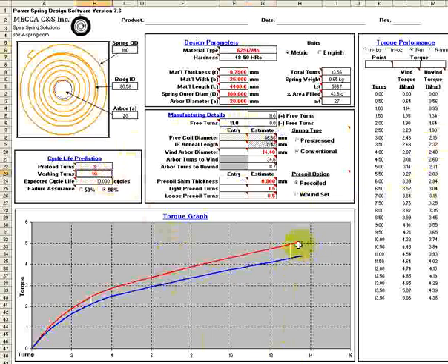This design also allows some safety turns to avoid a fully wound condition that could reduce cycle life. To determine the specific point at which the torque is expected to meet 2 Newton meters, turns can be entered to interpolate the point value.